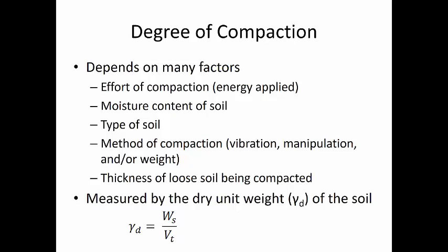And the method of compaction, depending on the type of soil: will vibratory effort and energy be better than weight or load, depending on the soil type? Vibratory is usually better for looser sands. Manipulation and weight are better for clays, but also okay for sands as well.